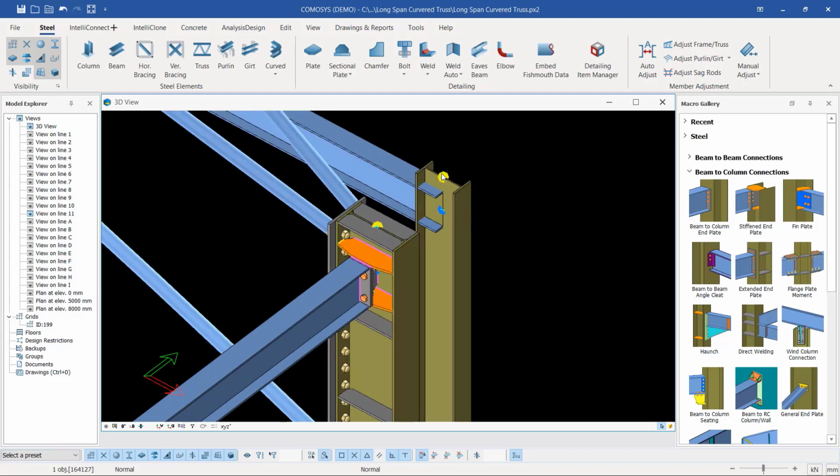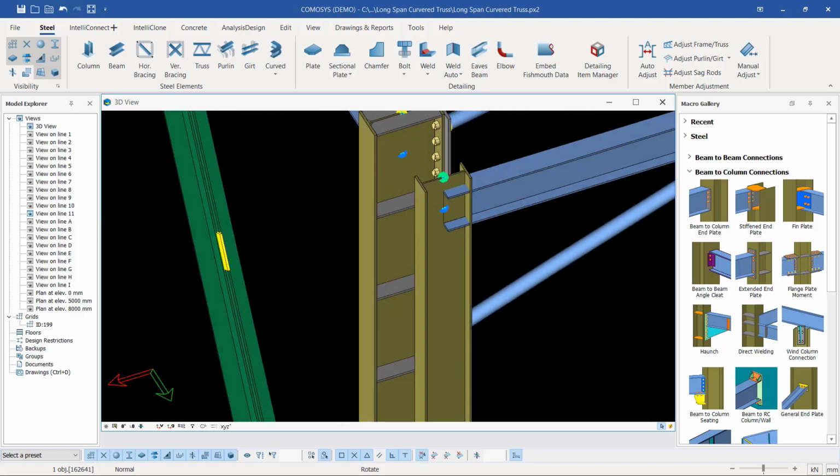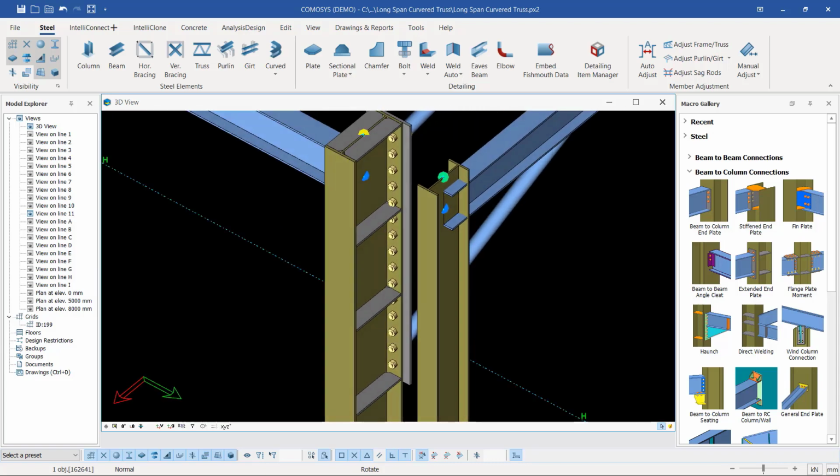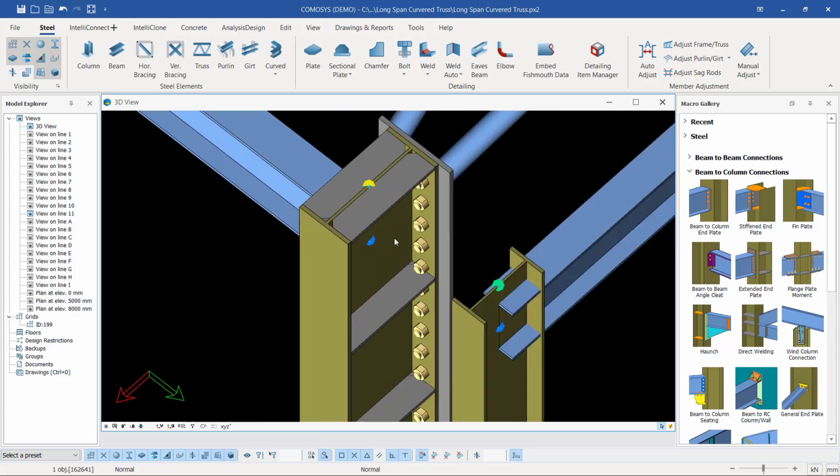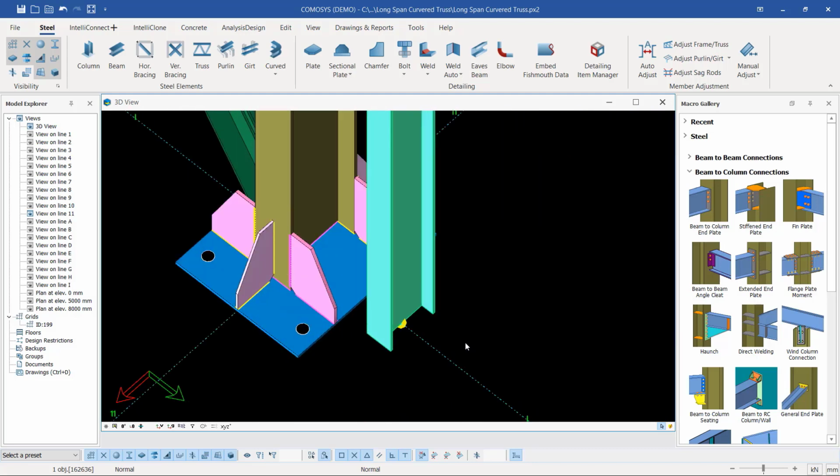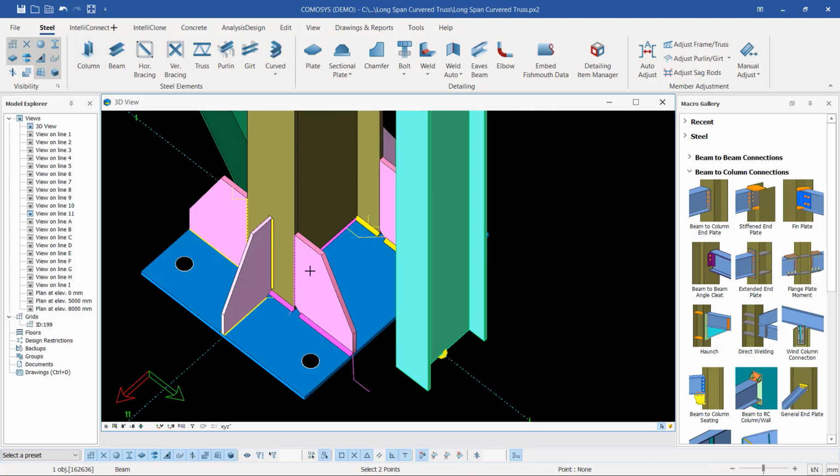So if I come and select this joint here, then right click and hold, I'll be able to turn around that. So I want to create a connection between this column and this. So I want to link this column and this column by tie beam. So how do I place that tie beam? I'll come to beam here and still, then I'll just mouse over my cursor over that until I see a red snap there. I'll snap on that spot and snap on this spot.